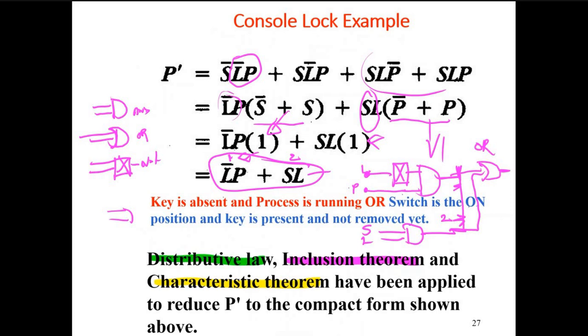So, $1, let's assume, for wires and chips and whatever. Let's assume a little printed circuit, mass produced, maybe $2-3. Then you hire somebody to put this together, solder, whatever. Pay another $10. So totally under 20 bucks. You might be able to get a little circuit board with all the components populated. And once you do one, go to your printed circuit production. You don't need to have somebody solder all the wires and so on. The surface mount process will do it all for an even much cheaper price.